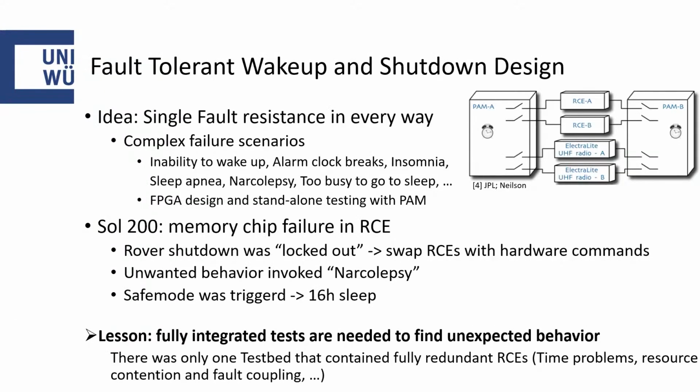Now I want to talk about the fault-tolerant wake-up and shutdown design and its problems during operation. First of all, what is a wake-up and shutdown design? The rover works in the day and sleeps at the night, simply speaking. So there has to be a system that wakes the rover up in the early morning, boots up the main compute units, and in the evening shuts it down to save energy and charge up its batteries overnight.